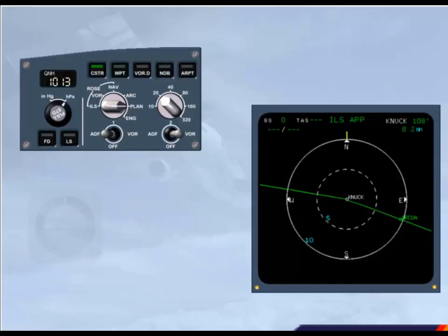As you have seen in the EFIS chapter, the mode selector enables the pilot to select different ND modes to display flight plan and nav aids data. Plan mode is recommended when entering and checking the flight plan. However, notice that nav aid data cannot be displayed in this mode.